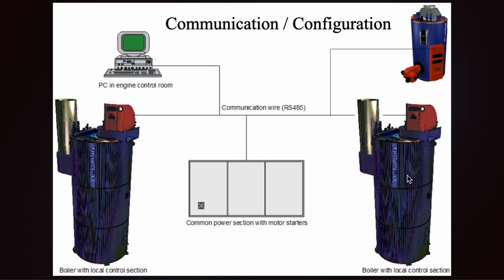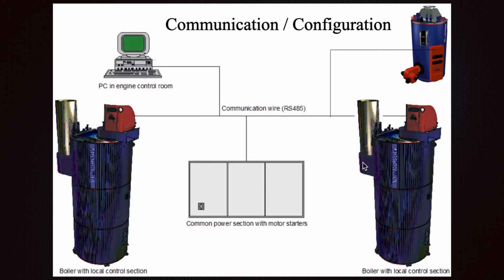It starts and stops because the demand is not so high, and the reason the boiler starts and stops is that it's a really big boiler. It increases the pressure to 10 or 9 kilograms, stops, and then slowly the pressure is reduced until 6.5 or 5.5, depending on the settings you have set on the boiler, and then the boiler will start again and reach the pressure that you have set up.